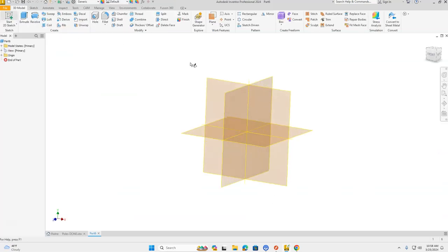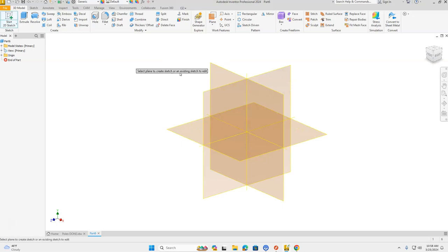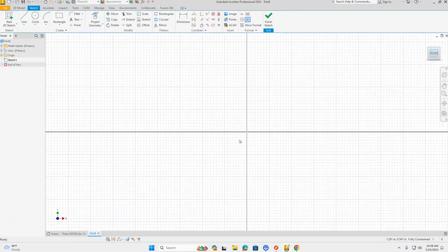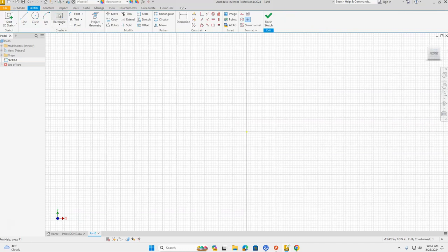2D sketch, the drawing with the green plus mark on our XY plane. Click Front in our World View Cube. Once again, we're going to choose our rectangle tool, and we're going to start at our origin. Once you get your green dot, click, let go of the mouse click, and stretch out a rectangle. Our radius for our horizontal dimension is 2.